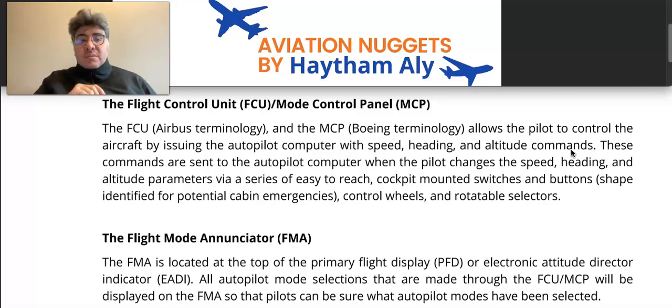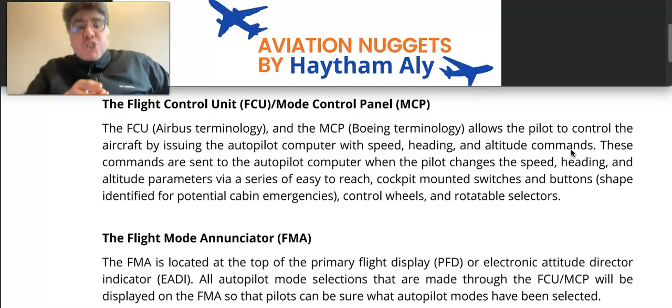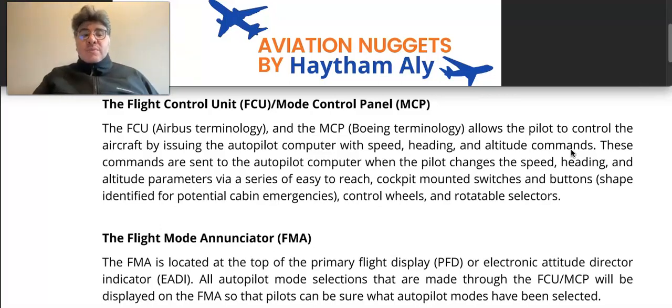And from this knob, we can always remember: push to manage and pull to select. If you push on the rotary selector, push to manage. Manage what? You say to the autopilot computer, manage the speed, or manage the heading, or manage the altitude. I'm the pilot giving you, autopilot computer, the authority to manage the heading or speed or altitude or maybe vertical speed.